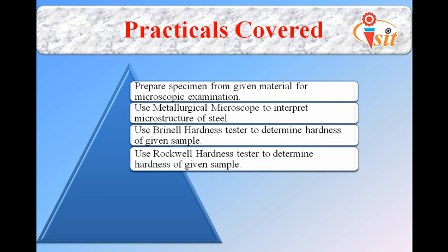The Rockwell hardness tester is used to measure the hardness of those materials which have high hardness and short or low thickness, because in the Rockwell hardness system it doesn't give a high load. That load may be between 50 kgf, 100 kgf and 150 kgf, as in the Brinell hardness system we give a load of 3000 kgf. So it matters what load we give to the material. It matters because due to the low thickness and high hardness, with a high load that material may break.